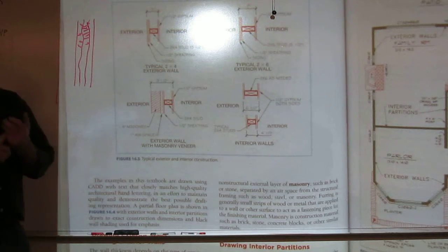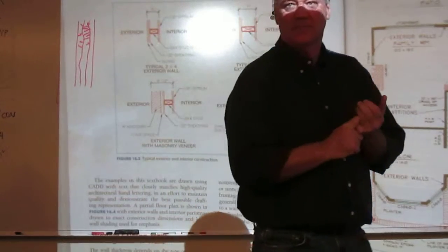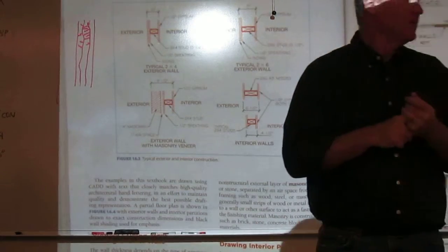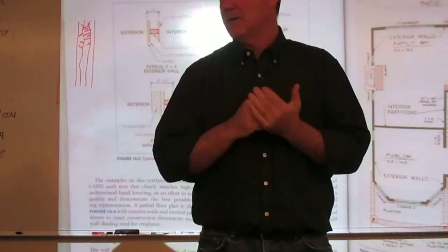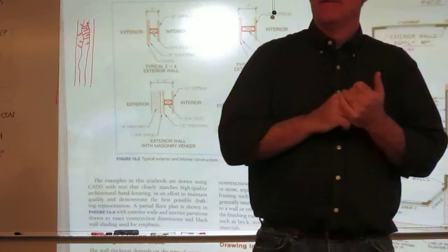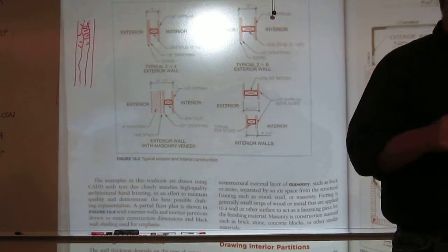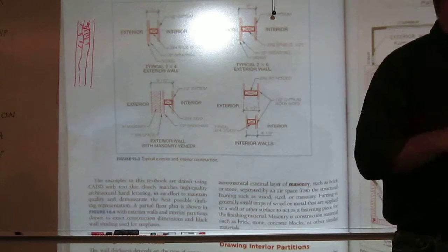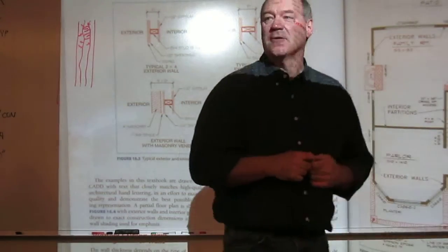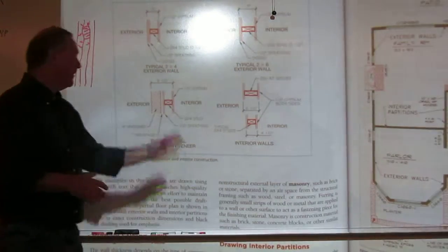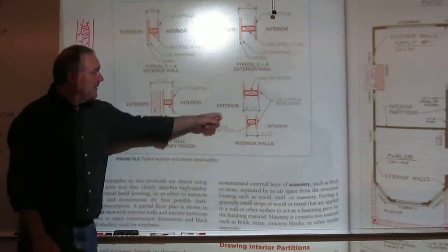You need plumbing walls. Now, that only occurs in the floor below a bathroom. The reason is we need to have 3-inch plumbing at a minimum for a toilet. So when we bring it through, if you have 3-inch plumbing, that's the interior diameter of that pipe. It's actually 3 5/8 or so. It doesn't fit in a 2 by 4 wall. So we go 2 by 6, and it's strictly to carry the pipe. That's the only other reason we really do it in our area. So these are wood walls.